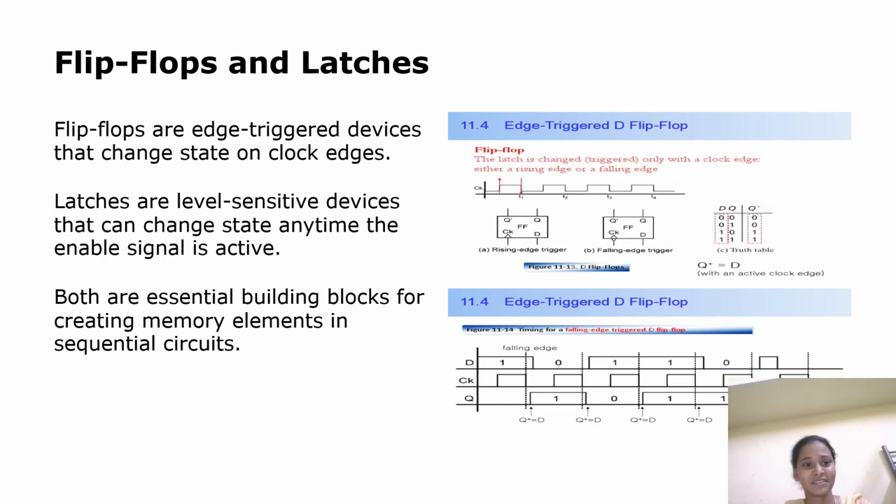Flip-flops and latches. Flip-flops are edge-triggered devices that change states on clock edges. Latches are level-sensitive devices that can change state anytime the enable signal is active. Both are essential building blocks for creating memory elements in sequential circuits.